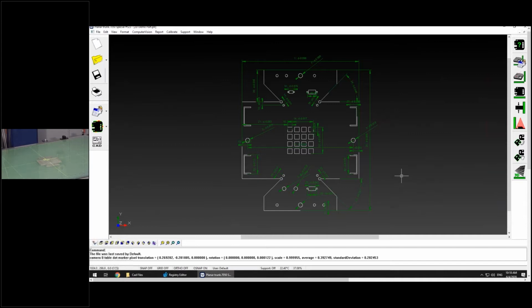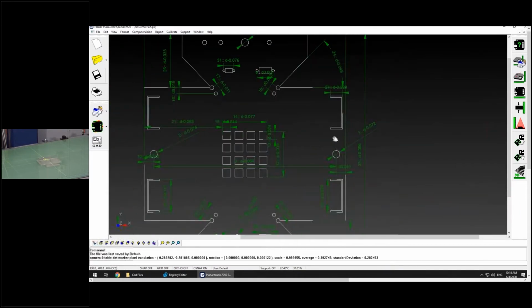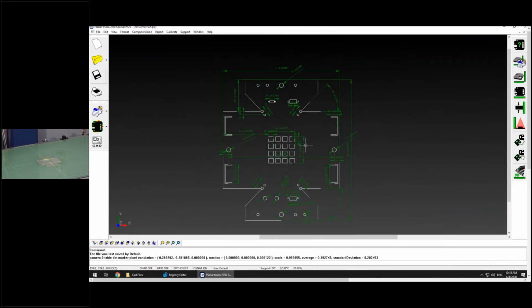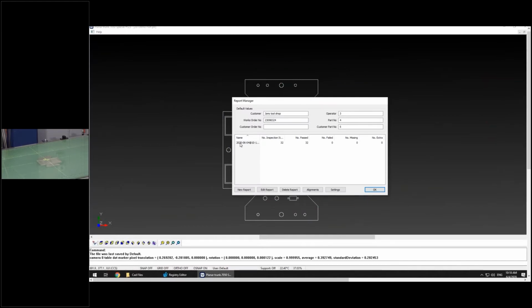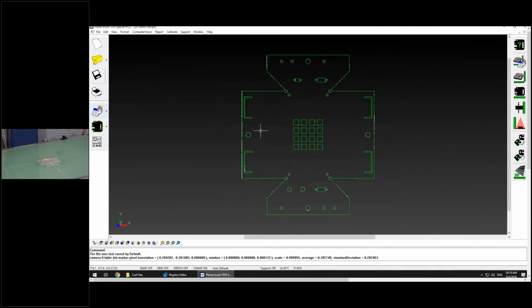I do have a couple of customers that love this because they actually wanted their operators to take note of certain values. They need to see what this number 3 dimension hole is. They need to see what the overall deviation is here. So different ways to run it. Now again, you kind of lose the cool ability of the surf scan displaying green onto the table. But if all you care about for your specific methods of measurement is the true dimensions, you actually can skip the steps of teaching the operators to go into the inspection report and double click on the first value and then finding things from there. You can just use this diagram view and look at it from there. So another way of running the system.